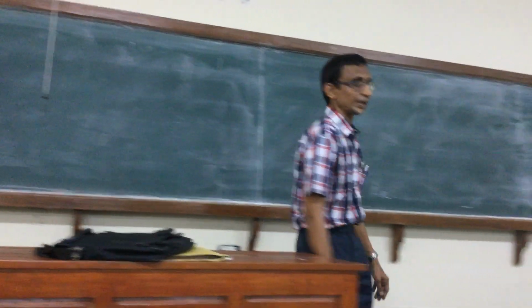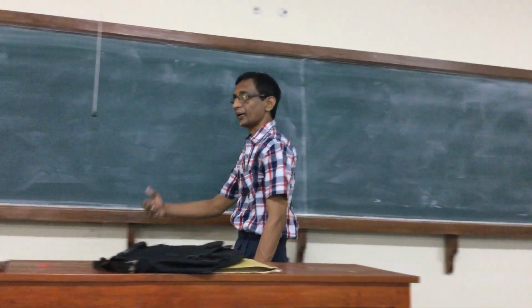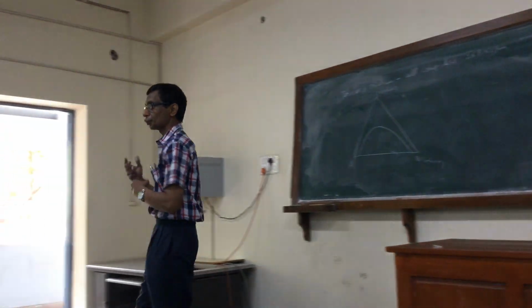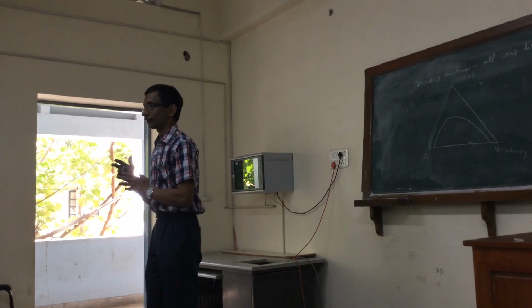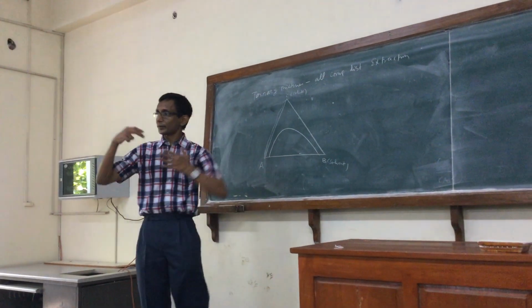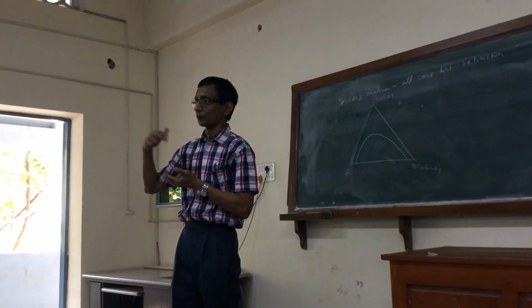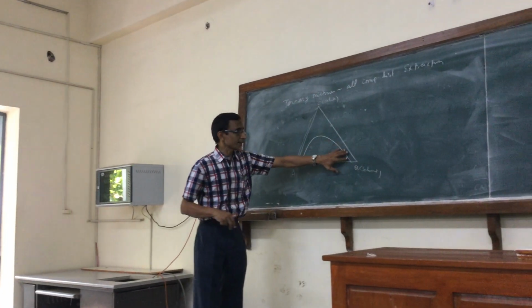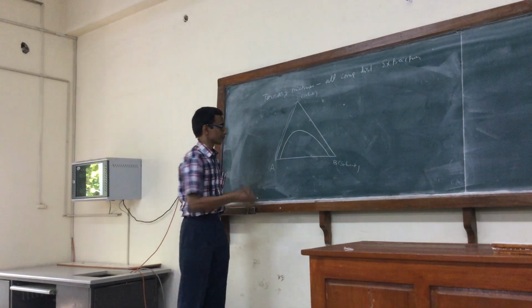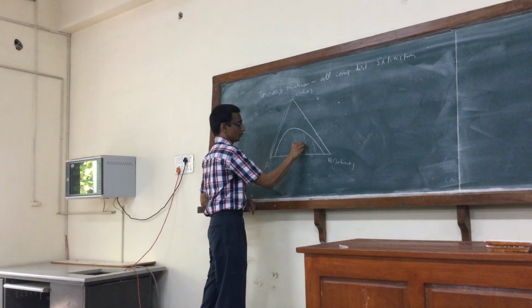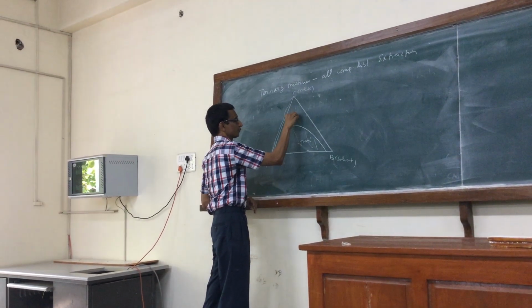So what does it mean? Right? So it means that again, as in the case of distillation, there will be one phase envelope which has two distinct parts actually, you see. Right? So the phase envelope in distillation separates the two-phase region from the single-phase region. So same here. So everything inside this region is two-phase. This is all one phase.